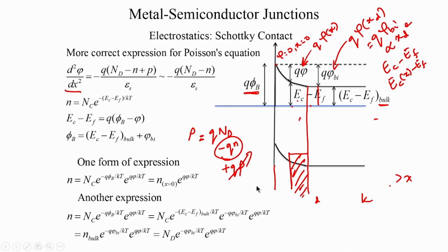But there is no need because we have no information, and in fact it actually makes the mathematics a bit more symmetrical if you keep the p, but just for the sake of an example I have not retained the p. So, we say that okay, the p is still negligible because it is an n type semiconductor, and in the depletion region as I approach the bulk I have this to be my charge carriers. Okay. So, that is my